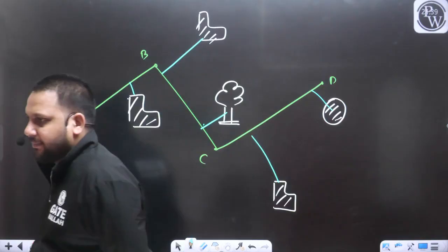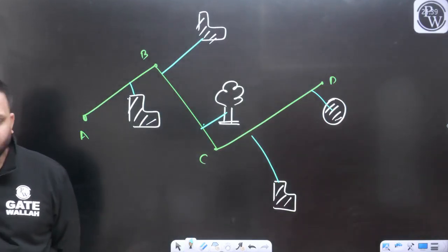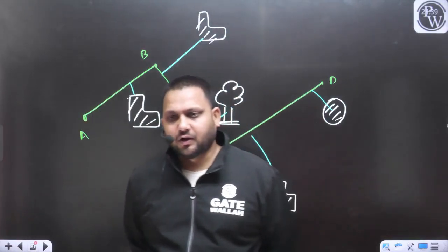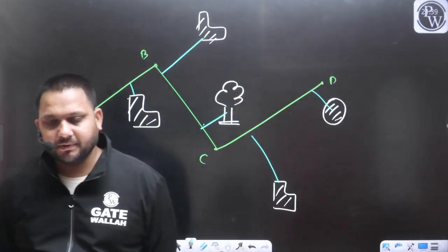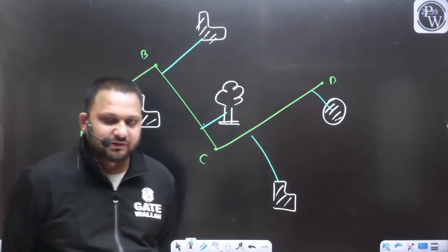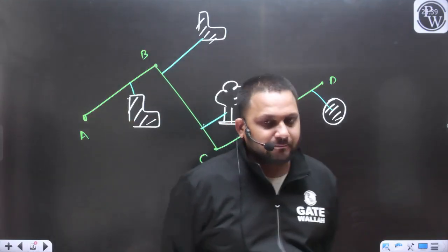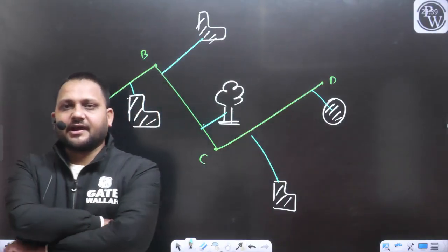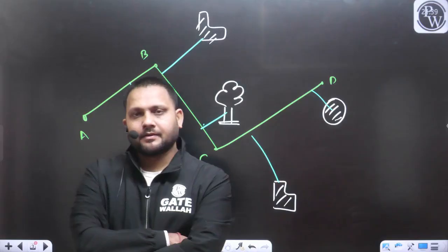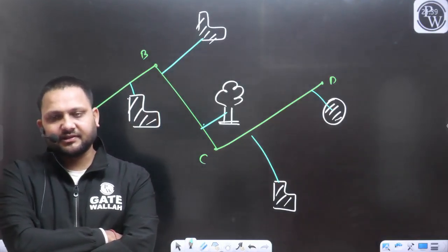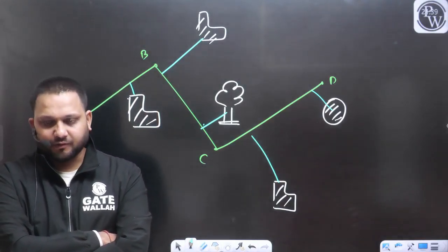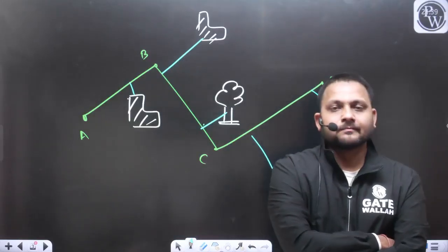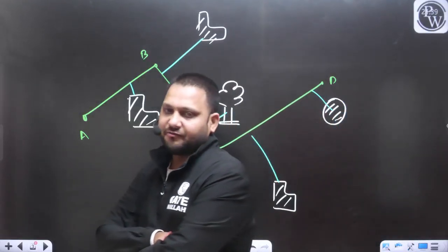Similarly, if there are 3 points defined on the ground, existing on the ground, as well as available on the previous map, and with the help of these three well-defined points we are locating the position of the plane table, that will be considered the 3-point problem. So this was the discussion related to the methods of the plane table. I hope the discussion is clear to everyone.